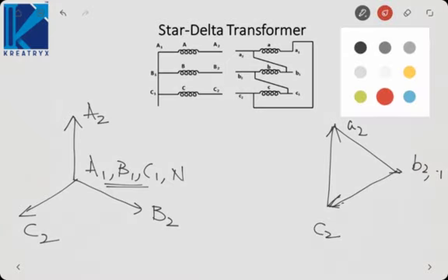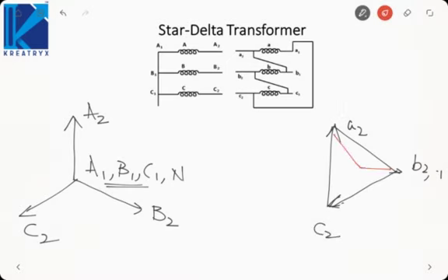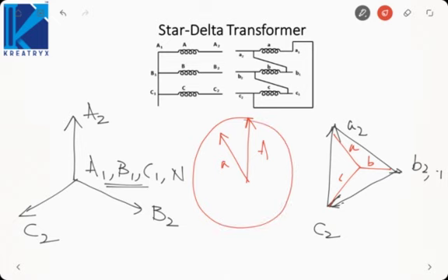Now we will draw the reference phasors. This will be A, B, C. Okay. Now if we plot on a clock, capital A is like this, small a is like this. So if we name the connection, it will be YD11. Okay. That is, we are getting a 30 degree anti-clockwise shift. So it is 30 degree leading. So it provides a phase shift of 30 degree leading.